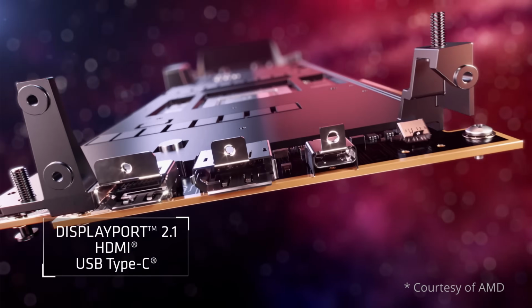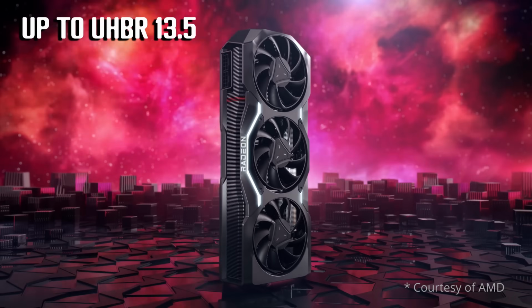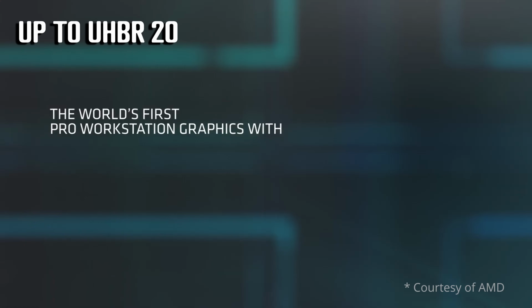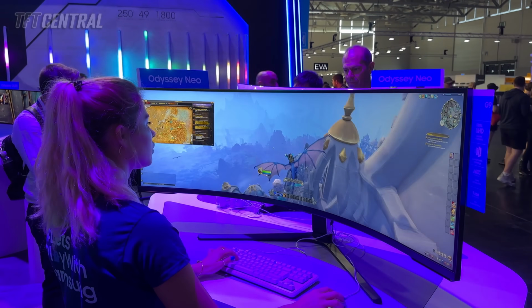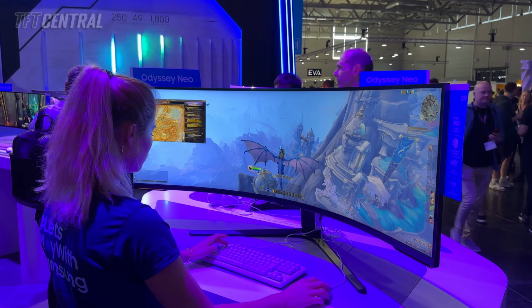AMD do have a couple of graphics cards that support DP 2.1, including their top-end consumer cards which have up to UHBR 13.5 speeds, and some professional and very expensive cards which can support the full UHBR 20 speeds. That at least allows some co-development of DP 2.1 displays, like we saw with the Samsung Odyssey G95NC, which needed DP 2.1 to power it and was co-developed with AMD using their UHBR 13.5 capable cards.